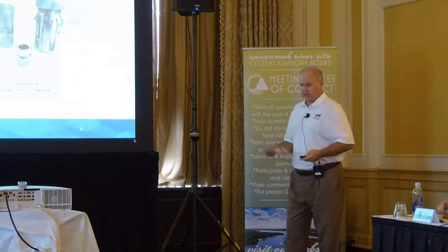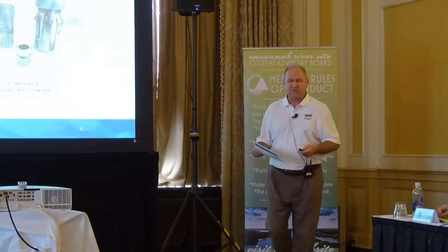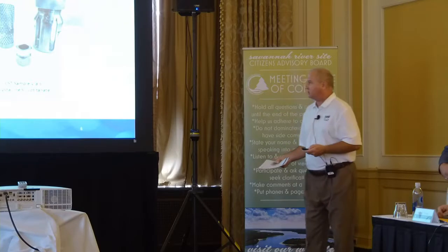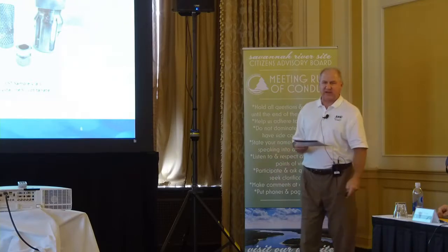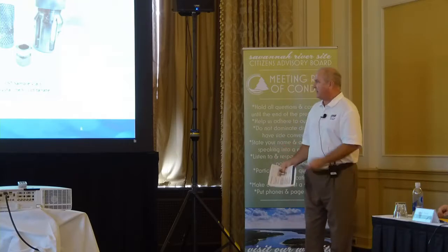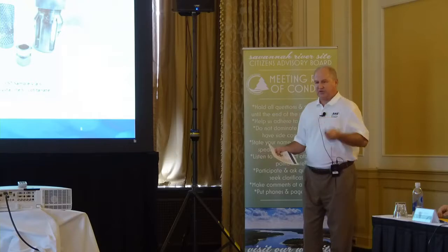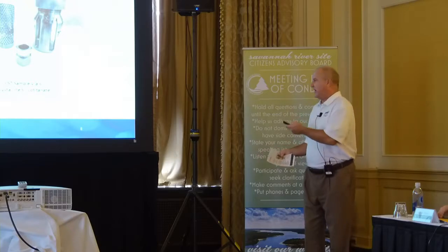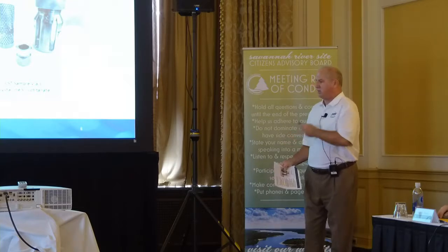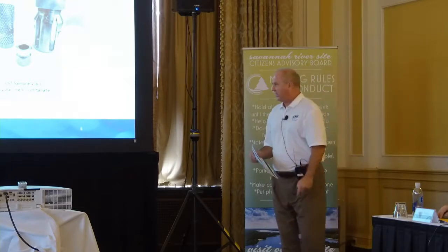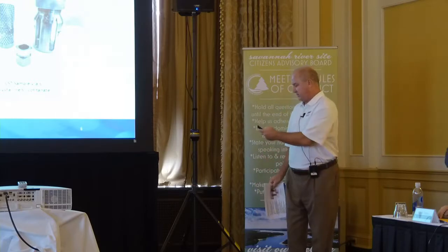We did that. Our DSA requires that we achieve 3.2 molar sodium. We did not achieve that for batch 1, and so we had to remediate the tank with about 16,000 gallons of sodium hydroxide. Once we did that, resampled, and achieved our qualification goals and our sodium molarity, we were then able to process, starting in January, 152,000 gallons of salt, dissolved salt.